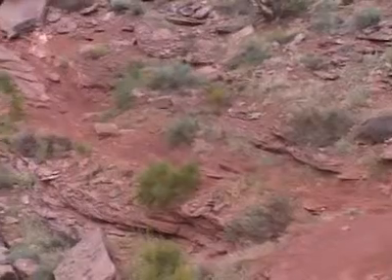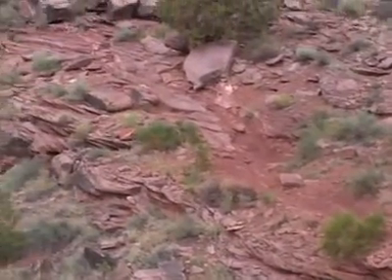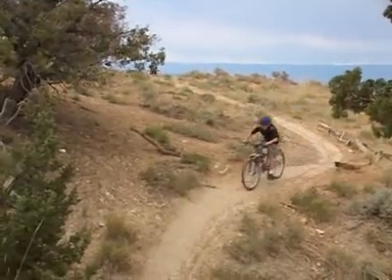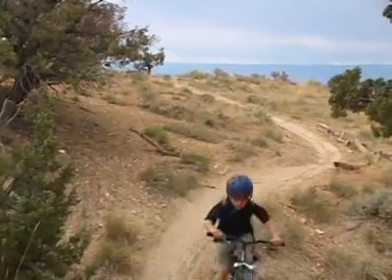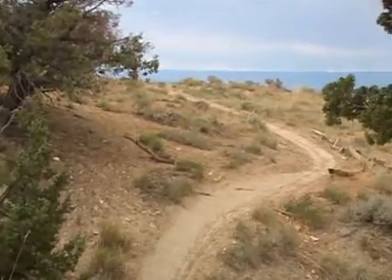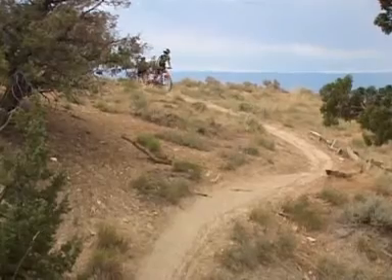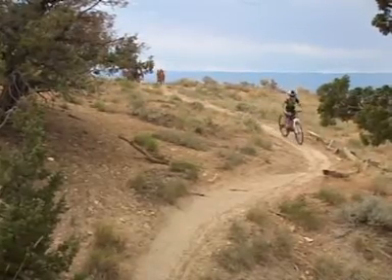For example, trail grades can be steeper on solid rock, but dry soils require more gentle grades. Determining the maximum sustainable grade requires careful evaluation of these factors and years of trail building experience. When in doubt, design with conservative grades.